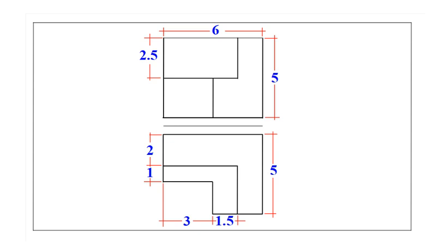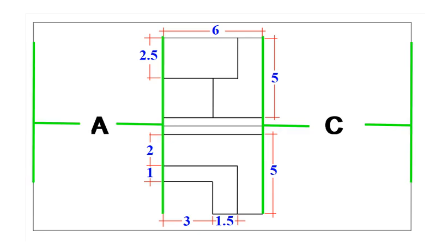It's all about balance. Think of your drawing space like a picture frame. You want your views to be centered and evenly spaced. First, the horizontal spacing. The distance from the left border to the side view should be the same as the distance from the right border to the top view. Let's call that distance equals C. This centers the entire layout left to right.